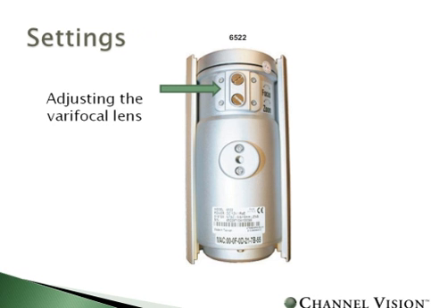On the 6522, we're showing you how easy it is to adjust the varifocal on it. There is a focus and a zoom with those two large flathead screws that you see on there, and then you adjust it to get the proper image size.